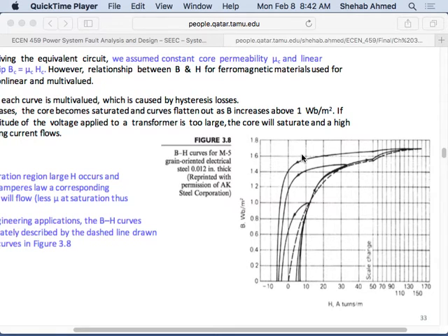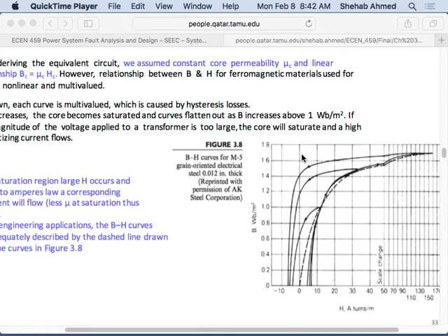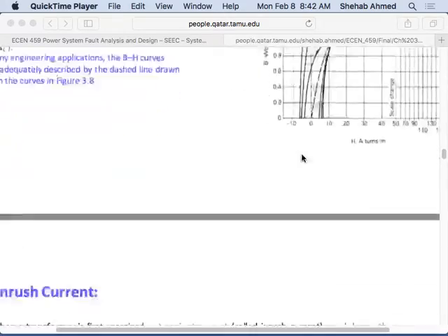During operation, if you put a higher voltage or if you're pushing a higher current in the transformer than you're allowed to, then you will find that the current you're putting in will not be contributing to additional voltage across the winding, and you're just burning power. This is during operation, right? So something to consider. We did not look at that in the equivalent circuit.